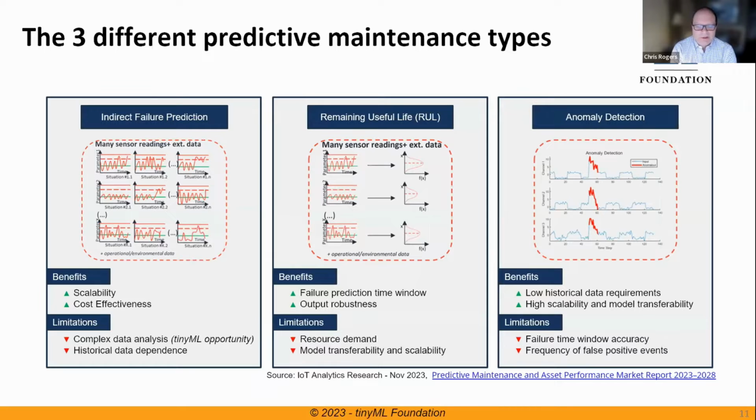As you might imagine, the biggest issue with this is the propensity for false positives, because the model doesn't know what is an interesting event versus just an event that's an anomaly, right? So in the factory setting, again, with that motor on a foundation, if somebody were to drive by nearby with a forklift truck and hit an expansion joint in the concrete floor, that causes a shock. Now I've got a vibration. The machine detects an anomaly, reports it. Someone rushes out to investigate, only to find that there was nothing wrong.